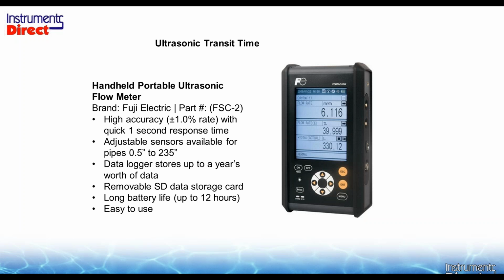Finally, we have a device with a data logger. Basically it stores all the data on an SD card, the same card that you put in your new camera, a 2 or 4 gig SD card, which basically means you can store data until the cows come home. So there is no longer a capacity problem as with the old data loggers. And you don't even need to use any software. You just take out the SD card because the file is saved as a CSV file. So you slap it in your laptop or your PC, turn on Excel and open the file. There's no software, there's no cable, and you're not going to pull your hair out using the data logger. So the technology is moving forward in data collection. It's got screenshot saving, so you can press a button and it stores the data.